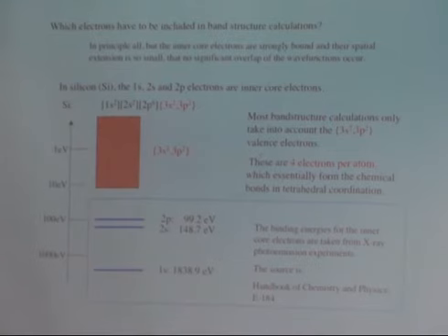That's how deep that electron energy is, and therefore, if you're making a device where we are only applying 0.5 volts, you're never going to see that electron. It's buried inside. But if you come in with an X-ray with 2 kilovolts of energy per photon, then you can kick this thing out. So that's a core level electron. Similarly, the 2s, 2p orbitals are very deep as well, 100 eV, 400 eV, and all that.